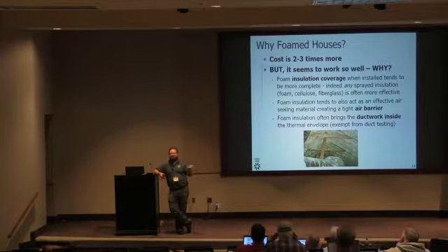And the name of the game is complete insulation coverage and complete air barrier. The problem is people don't really think about that. They don't think about the drywall and the ceiling as the air barrier. A totally new concept about how to build. Yeah, and so, I mean, that's the problem.